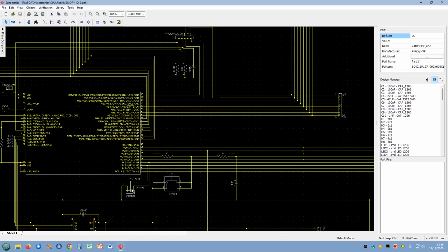So I'll put links from these COM ports here across to here. And then whenever the program wanted to put B0, B1, that's D0 or D1 on the data bus, I put a patch in the program to put it out of these ports here, and then I wire them across there. So I could actually control the board while having the programmer plugged in and actually single stepping the microcontroller. That's not the same as a single step of the CPU, it's actual microcontroller single stepping, because there might be 100 instructions on the microcontroller for one step on the actual CPU.